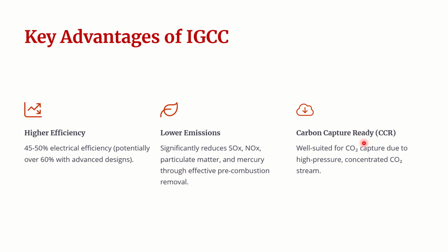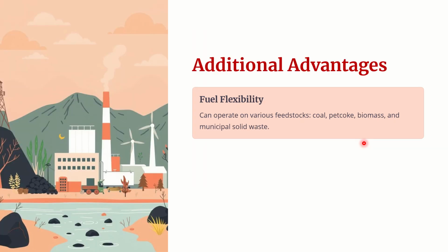Carbon capture ready. Integrated gasification combined cycle is inherently well suited for carbon dioxide capture due to the high pressure, concentrated carbon dioxide stream produced after the water gas shift reaction, making carbon dioxide capture more energy efficient than post-combustion capture in pulverized coal plants. Then some more advantages: fuel flexibility. It can operate on various feedstocks, including different types of coal, biomass, and even municipal solid waste.